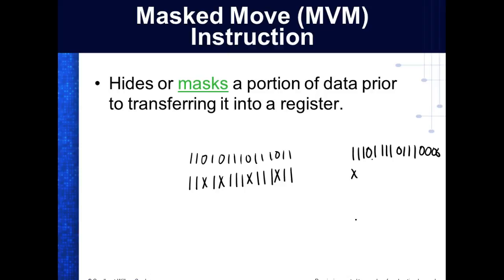You understand? What would this one be? This one would be a what? A 0. I don't care what the other operand is, because if I AND anything with a 0, the answer will always be a what? A 0. If I AND something with a 1, then it's going to depend on the other number. So what we do with an AND mask is we make sure that certain bits are cleared. We can use an OR mask to make sure certain bits are what? Set.